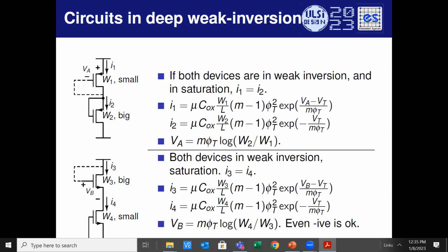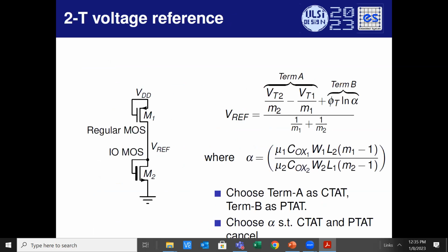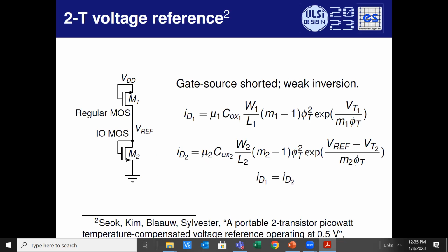We are talking about weak inversion because this equation for the MOSFET looks like a BJT only in weak inversion. And yes, this equation is really good. By now it has been quite well modeled and the foundries match with this model quite well. So there are no such effects. There is a lot of noise, but noise is something that you can filter out with an appropriate amount of capacitance.